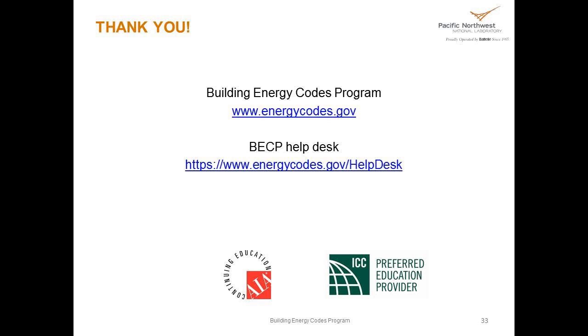So you can get flicker, and you may get premature burnout, and so on when the lights are dimmed. So you need to get drivers that are compatible with dimming. But they are available, and they should be commonly available. LEDs are actually great for dimming because you can control them very precisely and quite easily, and they are more amenable to dimming than, say, fluorescents.